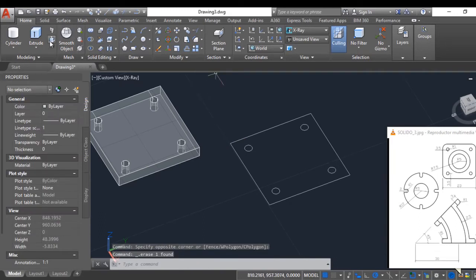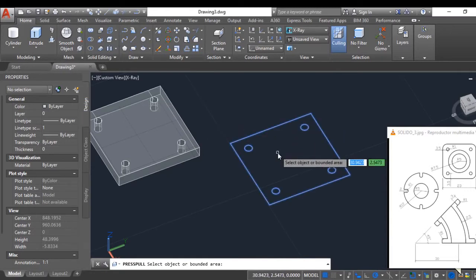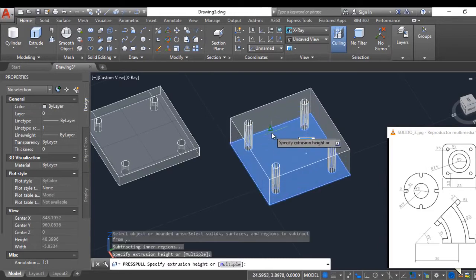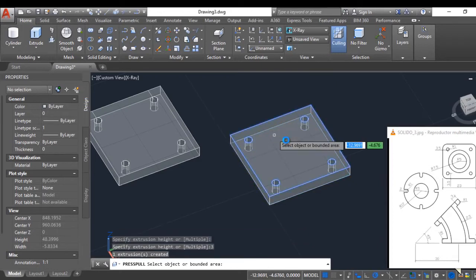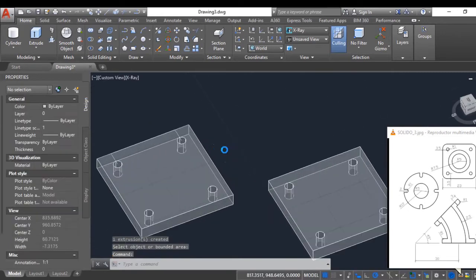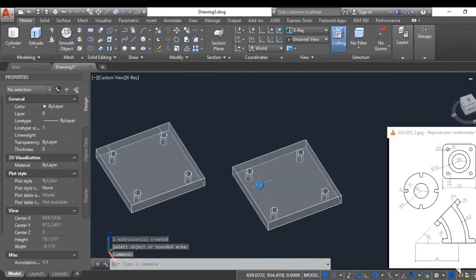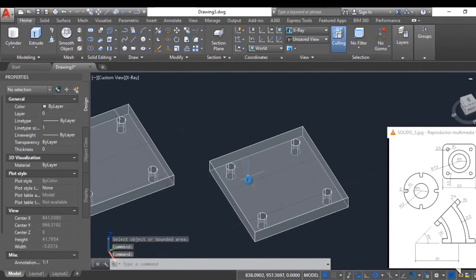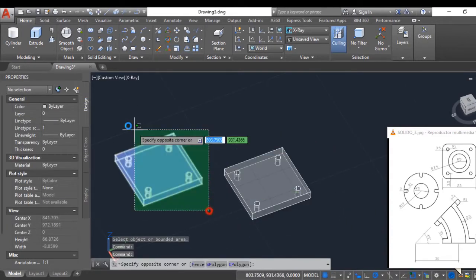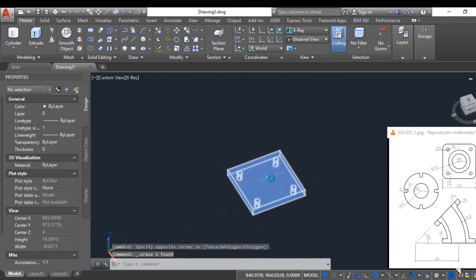I'm going to the press pull command, which is over here. I click and I see that the edges I need are selected, a type of extrude, which is the press pull tool. I click, and the next thing I do is place the measurement of 3, which is the thickness of this base. Right. Which is the way to do it, and we continue. We will continue with this here. And this we are going to erase, and we are going to do this part from here.